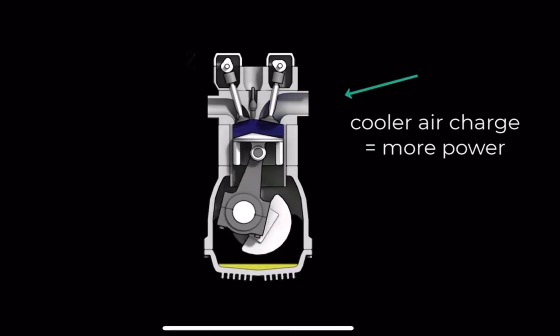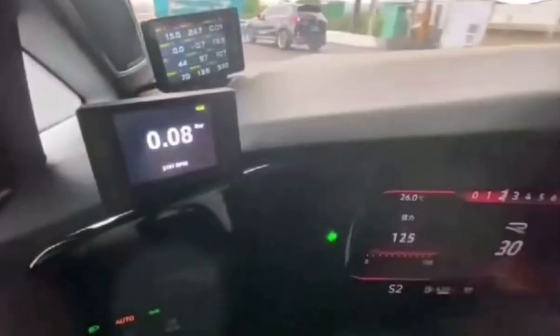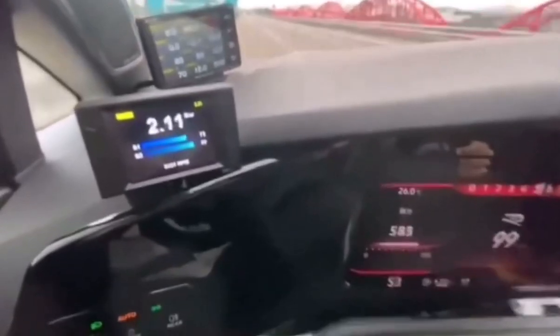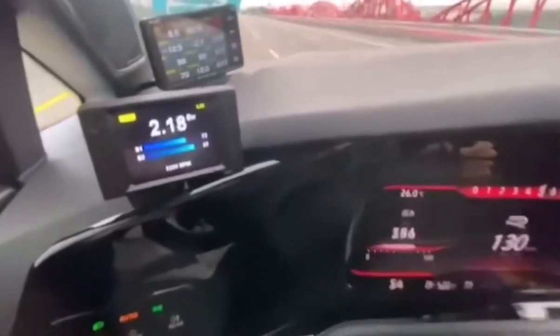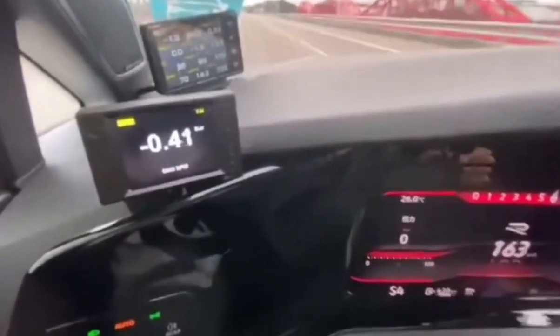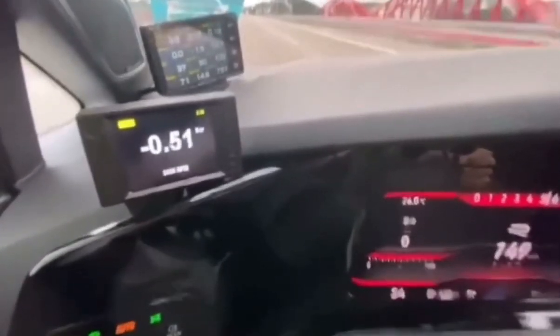Discover the power of methanol injection for your forced induction race engine. Ideal for turbocharged or supercharged setups, it cools inlet air, prevents detonation, and enables safe boosts and advanced timing. With Frostbyte as your go-to controller, experience power gains of up to 20% without the need for high-octane racing fuel.